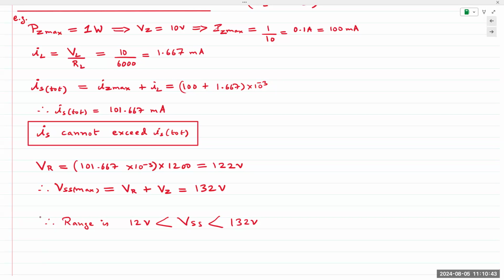This is the other way, saying that, okay, I have a 1 watt Zener, I worked off it, and I determined that I can apply 132 milliamps to it. But if you have a half watt Zener or a 2 watt Zener, and your supply voltage is never going to go above 50 volts, you might as well get away with using the cheaper option. So the other angle to look at such a problem would be from the voltage or the current. And again, the analysis techniques are still the same. There is nothing new about the analysis techniques. It's how you apply them that is new.